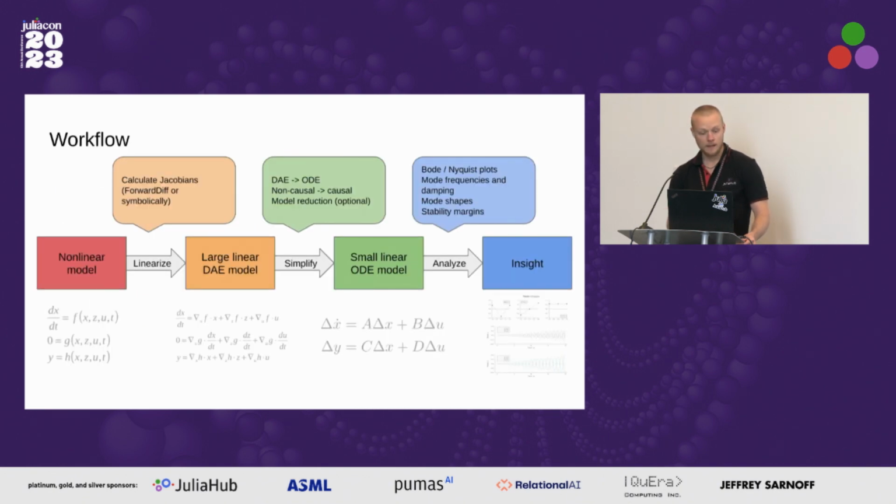All right. And the workflow here, this is a messy slide, but we start on the far left with a nonlinear model. So this would be our ModelingToolkit model. We perform linearization using ForwardDiff or symbolically. Then we obtain a large linear DAE model typically. We can perform some simplification on that if we would like, and then we arrive at a small linear ODE model. And then we perform more analysis on that linear model, and we arrive at some insight.